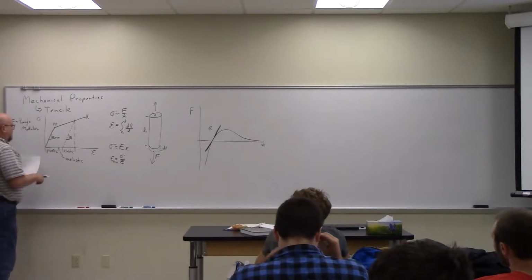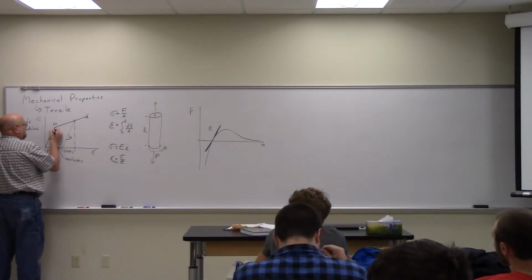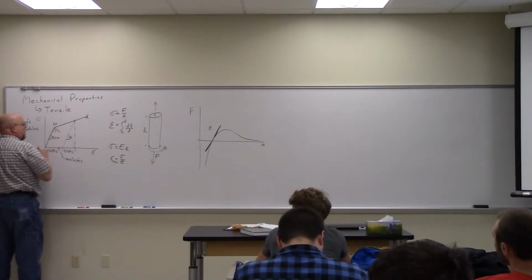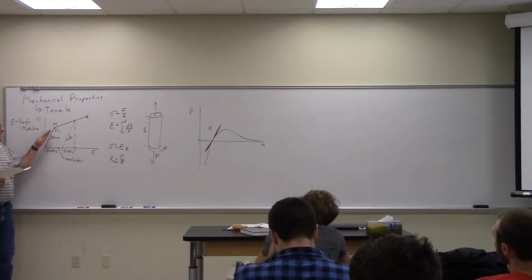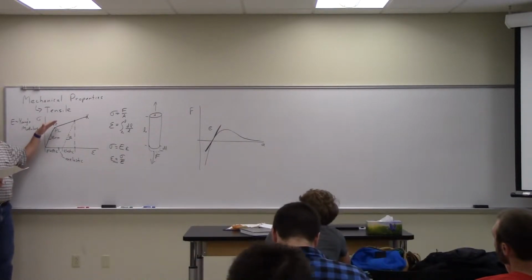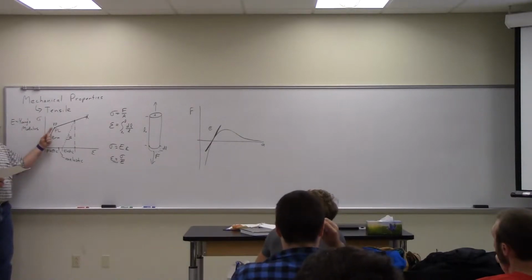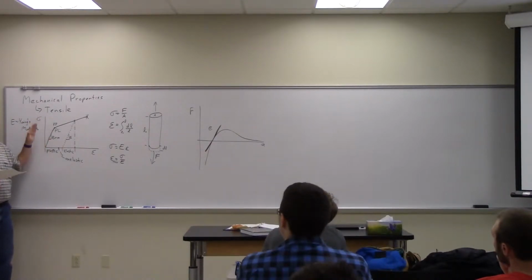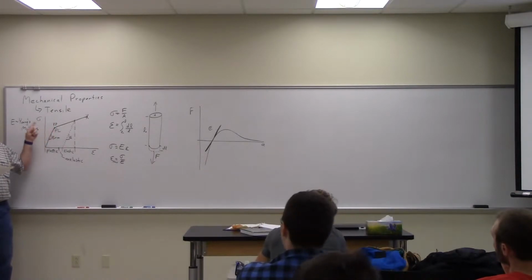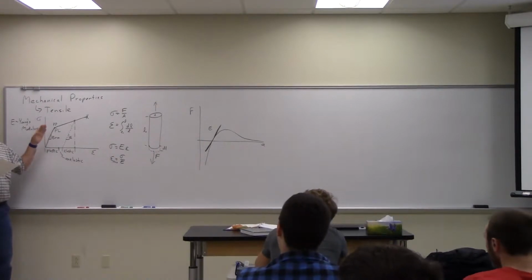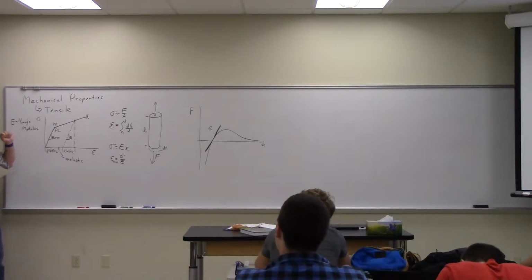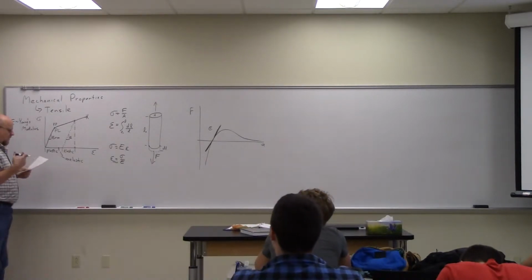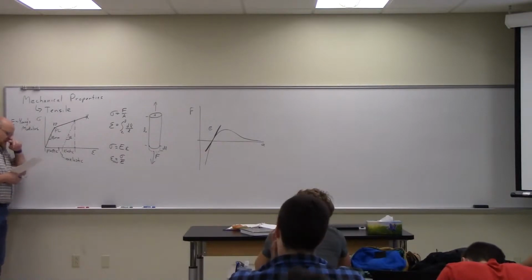Okay, a couple of things. So the yield point is there. There's actually sometimes defined a separate proportional limit. So back to Colin's question, I think it was Colin, about is there a little bit of bend after that? There's a proportional limit, which is the end of the linear region, that may be different from the yield point. They're very close to each other, they may be coincidental, but there is a separate definition of the proportional limit. So you can get some non-proportionality right before it begins to deform. So you may see separate definitions of those two points.